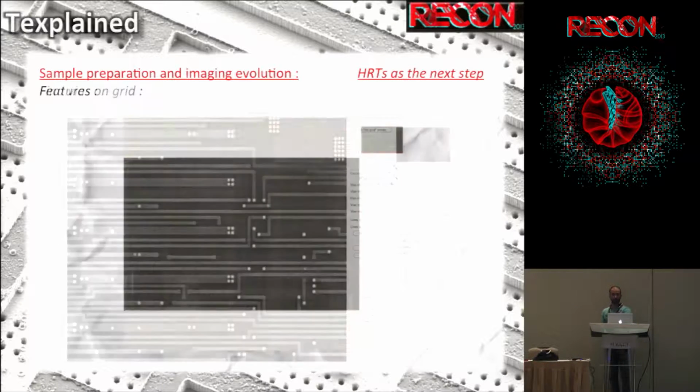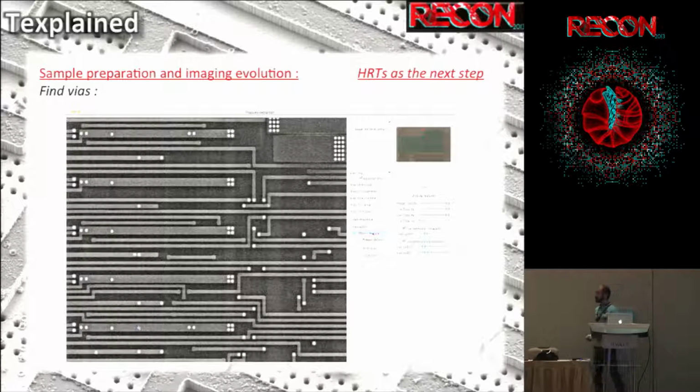Next step is detecting the thing which is obvious, so the white spots, the vias. So I just set some parameters. I guess it's pretty slow, huh? Let's be faster. So I'm setting up some parameters, and it takes maybe 30 seconds to find the right ones, just to identify all the vias on the chip. Your algorithm must also take into account that there can be some dust on the chip, and these are not vias, so you have to deal with the size of the via and everything. Then you tell the software to find the vias on the whole chip.